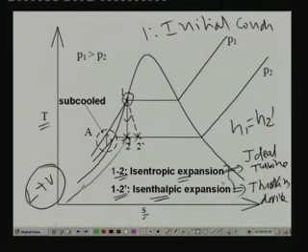Here the system means the fluid which is undergoing the expansion. So you must keep this in mind. The significant drop in temperature is taking place because during the expansion process vapor is being generated, and the energy required for vapor generation is supplied by the liquid itself. As a result its temperature drops, right? So this is the principle.